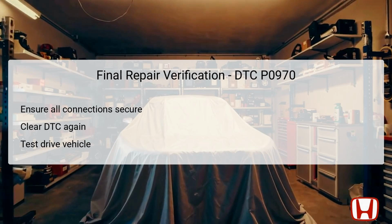Following the clearing of the codes, conduct a test drive to assess the vehicle's performance and confirm that the DTC P0970 does not reappear. Pay attention to transmission behavior and check for any abnormal symptoms. Successful verification entails not encountering any DTCs and restoring the vehicle to its optimal operating condition.